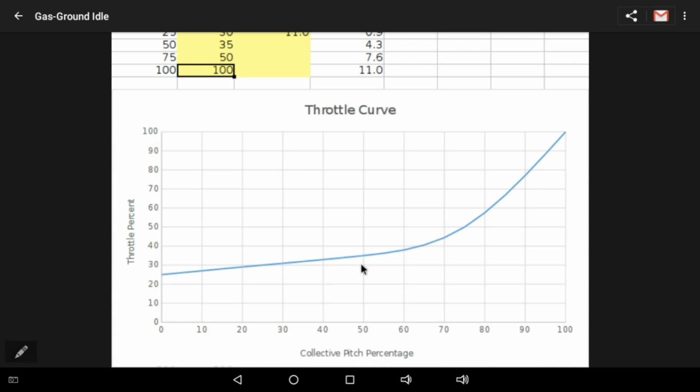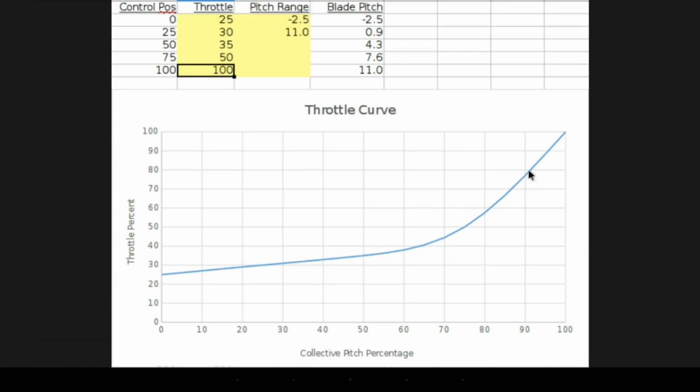So the same thing happens on landing with this throttle curve. You land it, you're going to be hovering right here. As you land, you bring the collective pitch down all the way to the bottom, and it reduces the power and the head speed. It disengages the governor right at about this 25% point, and it allows the rotor speed to drop down to ground idle, rotors turning.